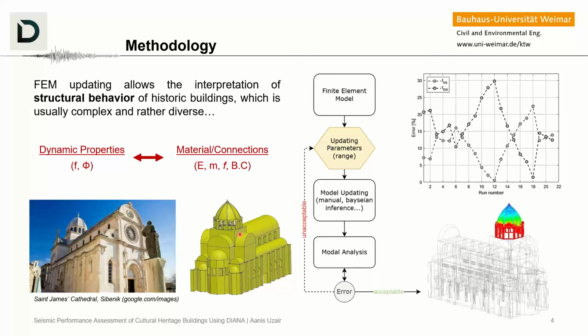for example, in this case, it's Croatia, I'm going to pick material properties which are most relevant or closely relevant to the case study in question. Once you pick the material properties, you do not pick specific values, rather you pick a range of material properties. So you say that if I have stone masonry, I can go from an elastic modulus ranging from this value to that value. So you always have a lower bound and an upper bound value to play within.